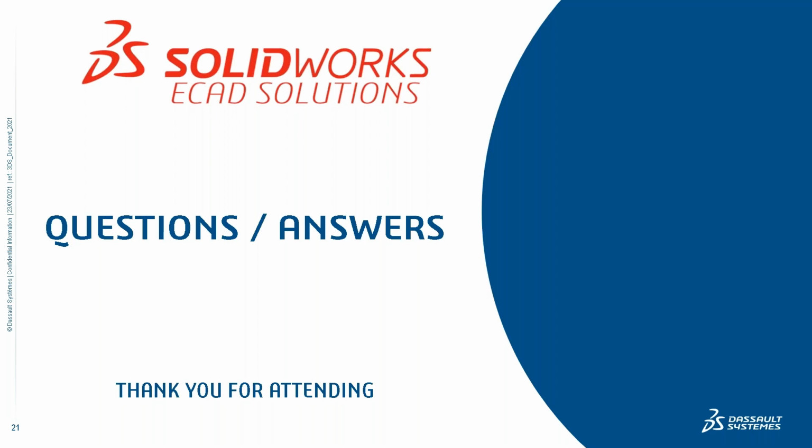I go into mechanical, select route cables, and keep it as all cables. It routes three cables. You can see them as individual little routes, but in the component tree they're represented by one subassembly, so you have one subassembly that highlights all three of those cables.